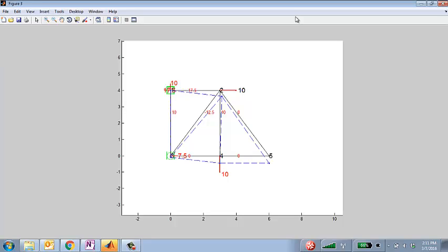To plot this truss, can you tell me how many times did I have to compute the internal forces of this determinate truss? Say that again. 14. Once to find the actual internal forces due to the actual loads, and then there are 5 nodes. So 2 times 5, 10 times I solved that. So a total of 11, right?